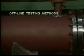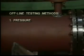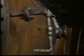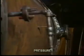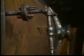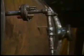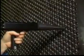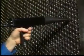In an offline environment, 3 methods for testing tubes are used: the pressure, vacuum, and tone methods. The pressure method is conducted by first sealing up outlets to prevent the gas from escaping and connecting house air to the inlet. The system is then pressurized. Test the system as previously demonstrated. Listen for the characteristic rushing sound of a leak with the ultraprobe scanning module.